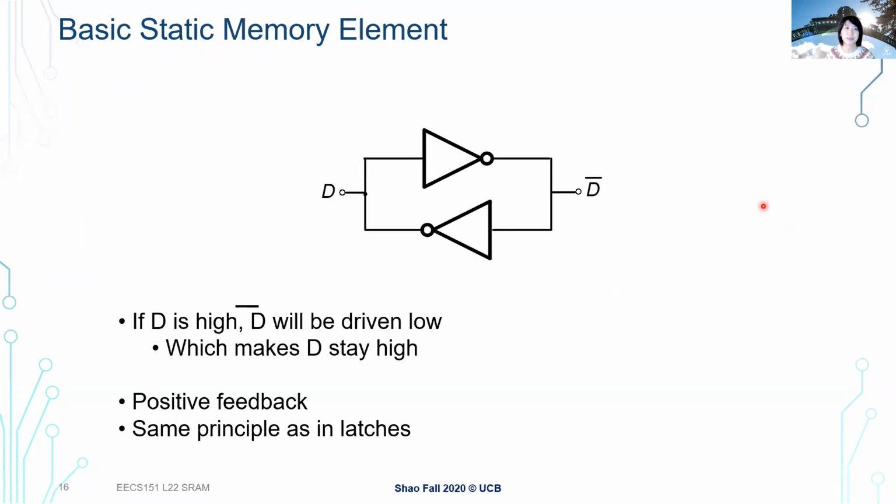So what does an SRAM cell look like? This looks fairly similar to our latches, right? Remember when we talked about storage elements, before we got to the latches, we always talked about there being some kind of cross-coupled inverters so that we can stably store a value, using the feedback loop and the regenerative property in our CMOS logic so that we can stably store either 0 or 1 in our circuit.